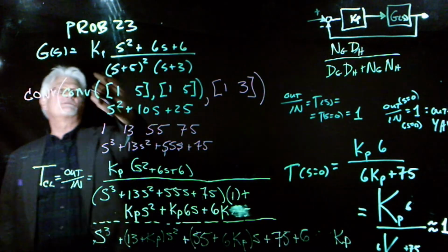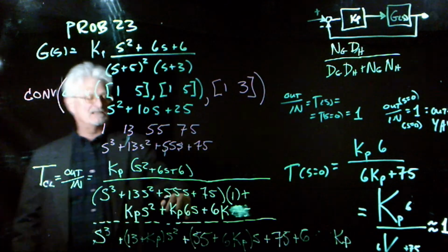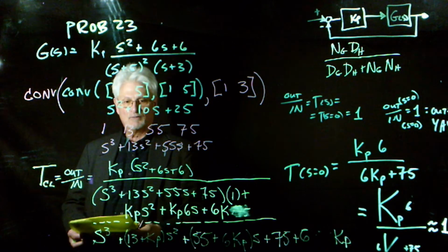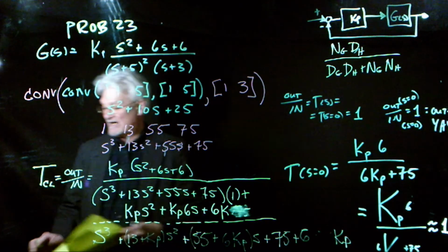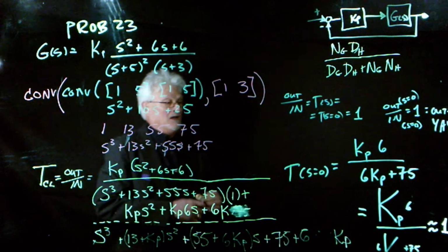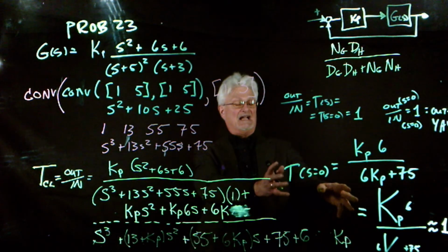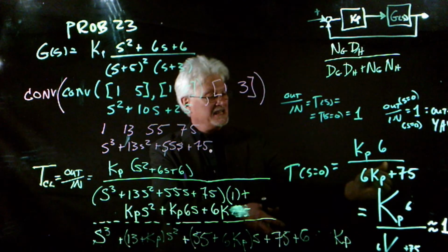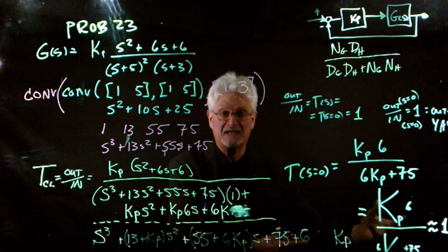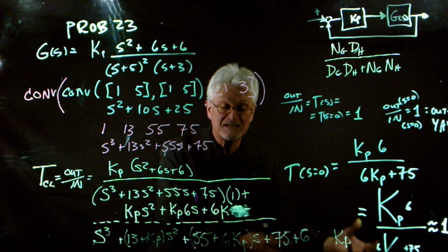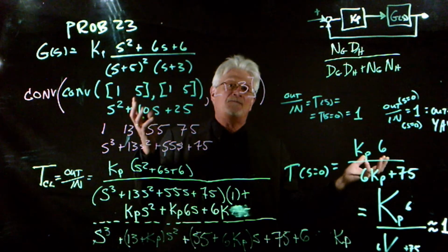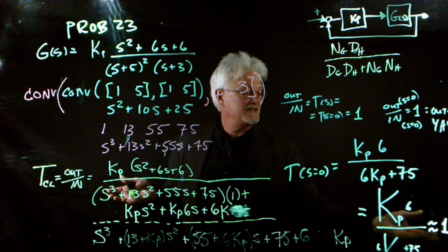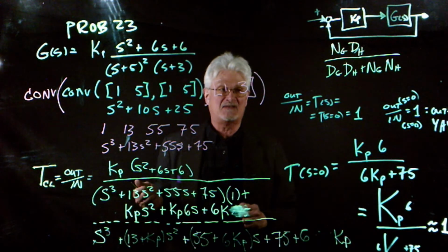All right, so what we've done is we've taken problem 23. They have a more specific set of formulas, which I may deal with in a minute also. But basically what I want to show you is that what we're shooting for is the steady state gain for our system. We get to choose this gain kp, and I'm hoping that in the homework assignment you're going to see there are some trade-offs. I can make kp higher and get more oscillations, but it makes the steady state gain better.